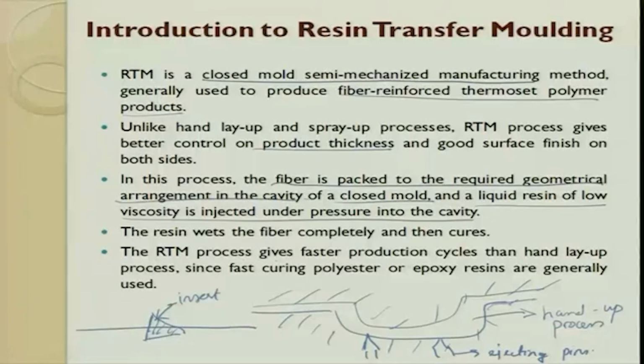So, resin transfer molding gives a faster production cycle than hand layup and a sound quality, since fast curing epoxies are generally used. Clear? So, you can choose, if you want to use polyester, fine. If you want to use epoxy, fine. Epoxy gives high strength compared to that of polyester.